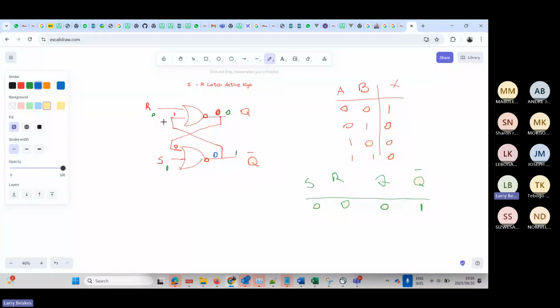So this will definitely be a 0 now. Then here we're going to take a 0. So we're going to have 0 and 0. 0 and 0 is going to give us a 1. We're going to have a 1 here. If we take this one, it will come here. Then here we will have 1, 1. 1, 1 is going to give us a 0. So 0 here, 0, 0, it will be a 1. This one, we bring it here. 1, 1 gives us a 0. So the final values here, Q is 1 and Q naught is 0, right?